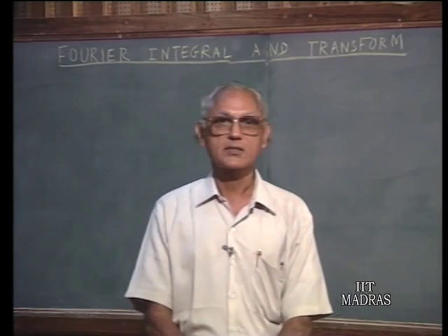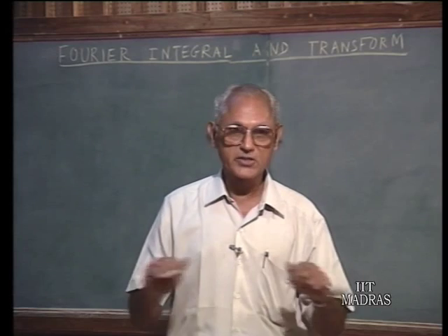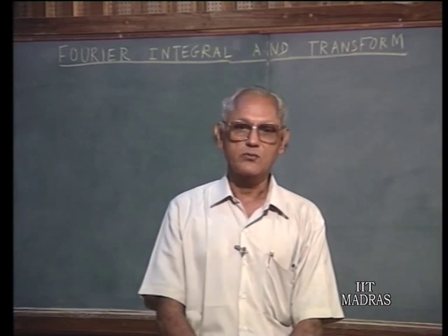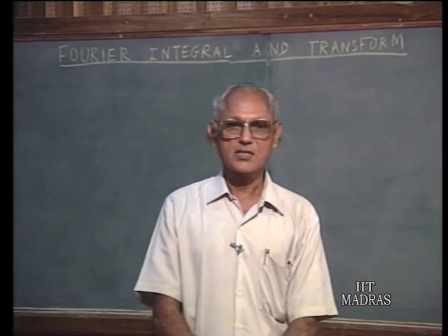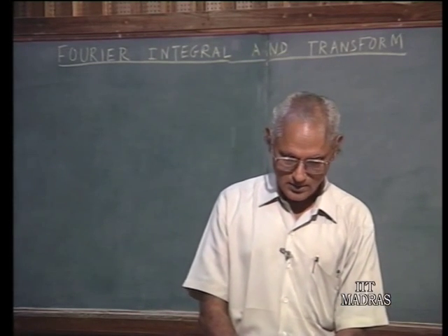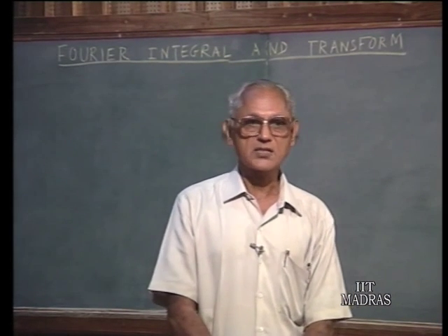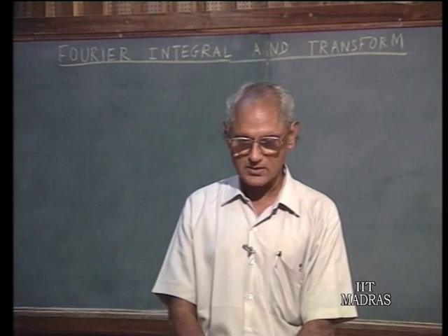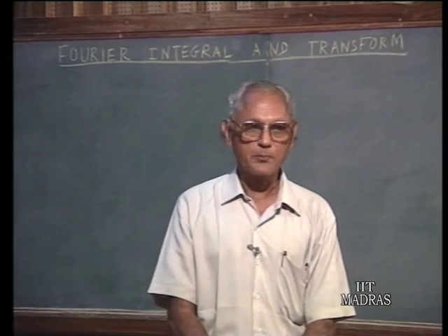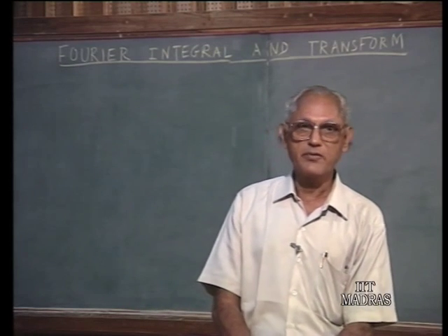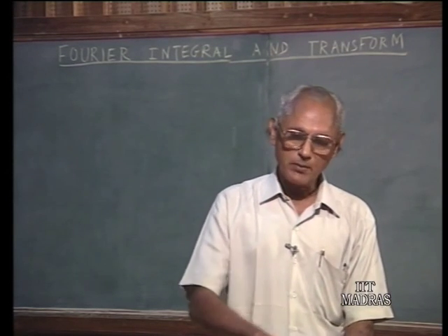Now, the Fourier method tells us that any such excitation function can be split up as the sum of tiny sinusoids starting from t equals minus infinity onwards and going up to t equals infinity. Now, each one of these sinusoids produces a response which can be evaluated using the steady state sinusoidal circuit theory methods, that is using these frequency response techniques, and then all these responses can be added up to find the total response. So, the sum of the steady state responses is what we obtain through the Fourier integral approach, and it turns out that the sum of the various steady state responses for the types of networks that we have talked about will also become 0 up to t equals 0.